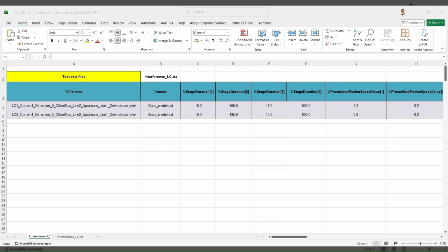This is important because VIV response and resulting DAF or DAF distribution can be affected by the actual buoyancy module arrangement, including module location, spacing, diameter, mass, buoyancy, and drag properties.